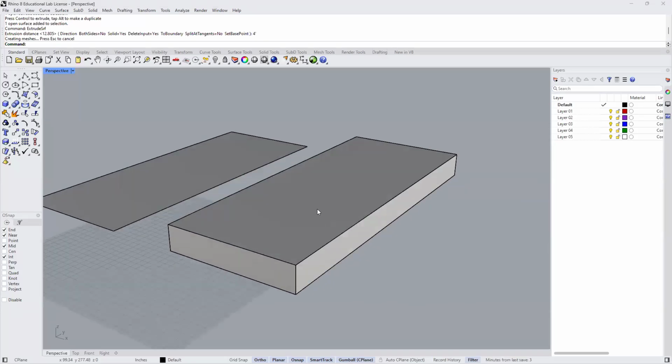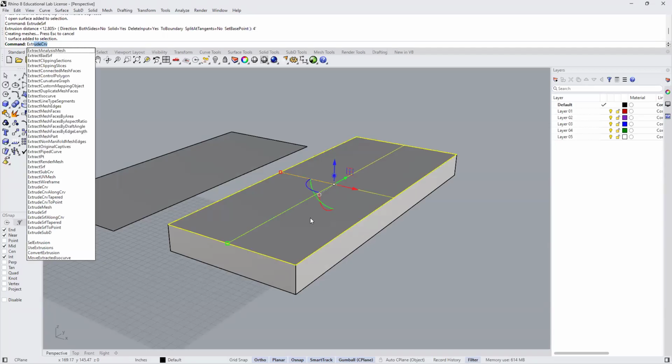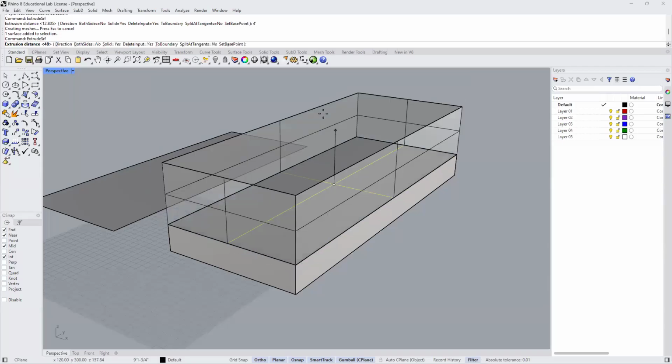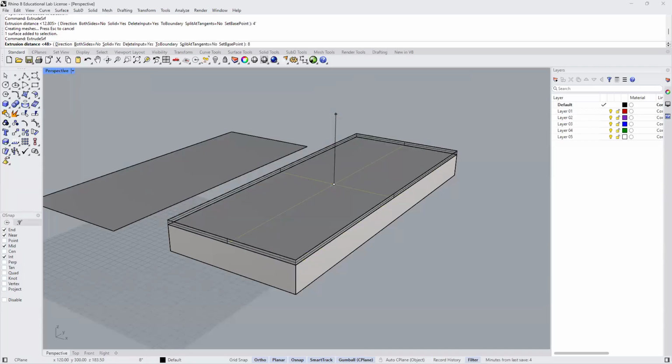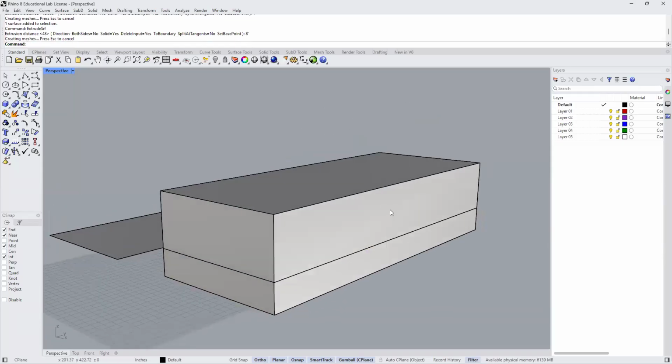And now what I'd like to do is go ahead and establish the other heights. So I can hold down Control Shift, click on it, and then I can extrude this again. Yes, I can use the gumball, but again, I'm just practicing this other command. So extrude surface, and there's the command. I could easily type it all out, but I'm doing it this way now. So extrude surface, I need to give it a height, and that height is going to be 8 feet, and enter.